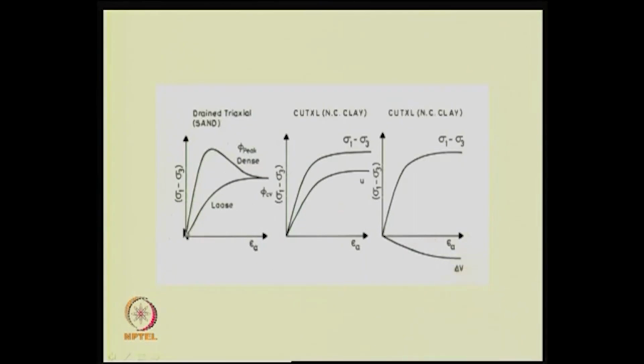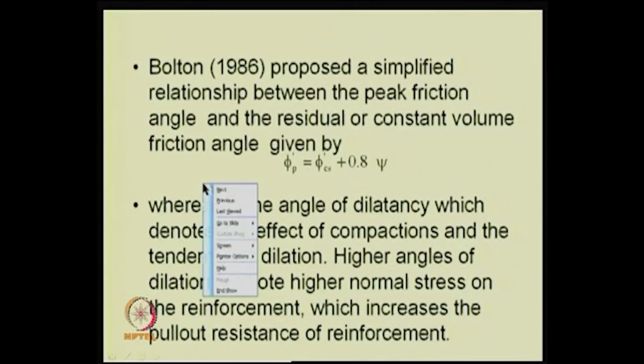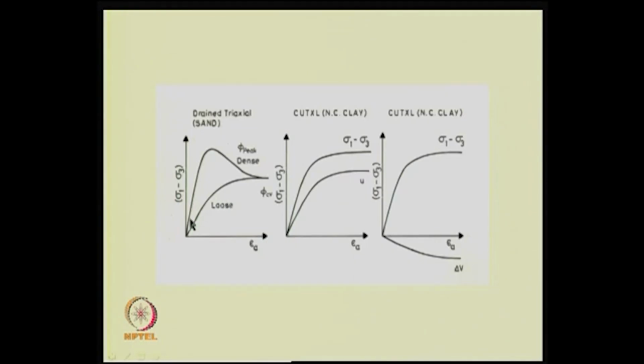Then there is another important thing I would like to highlight. See, the stress strain curve we have seen for the soil is like this, and for loose sand it is like this. If you have a reinforcement, it will be like this, much steeper. Okay. If you plot the reinforcement combined, soil plus reinforcement, it will be like this, much higher than either of these two, because it takes the load, right. So, why is it going to be effective? And one more thing is that